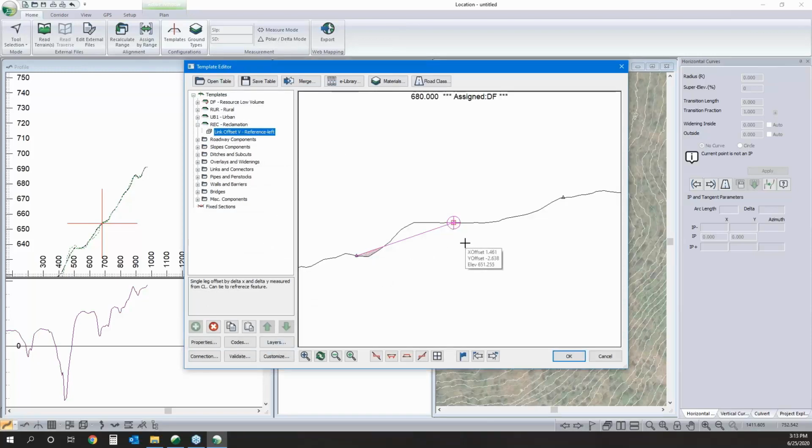So now, as Aaron introduced, we're going to have something that is a variable cut fill slope angle. Now we can move our center line, which is this attachment point, and the end of it's always going to be attached to that other feature down there. So if we drop our grade, we're in more of a cut, and a shallower cut into the existing prism.